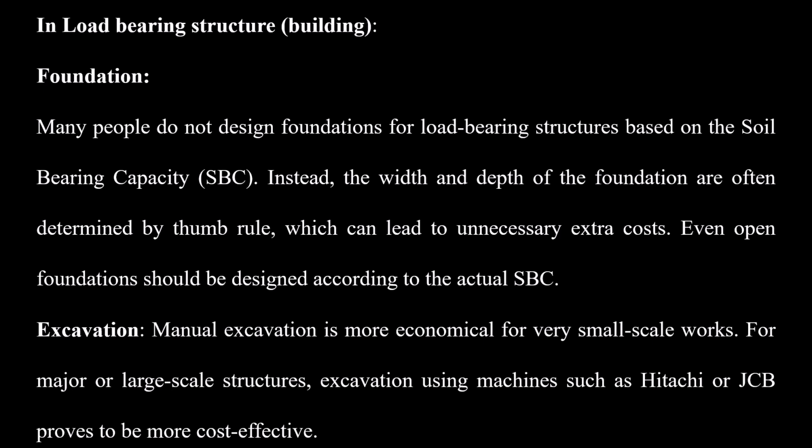In load-bearing structures, let us see the elements one by one. Foundation. Many people do not design foundations for load-bearing structures based on the actual soil-bearing capacity. Instead, the width and depth of foundation are often determined by thumb rule, which can lead to unnecessary extra costs. Even open foundations should be designed according to the actual SBC. Excavation. Manual excavation is more economical for very small scale works. For major or large scale structures, excavation using machines such as Hitachi or JCB proves to be more cost effective.